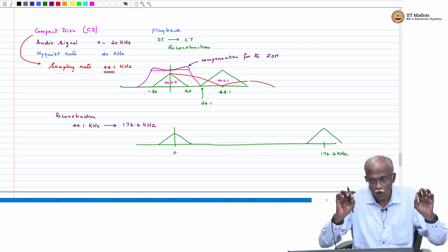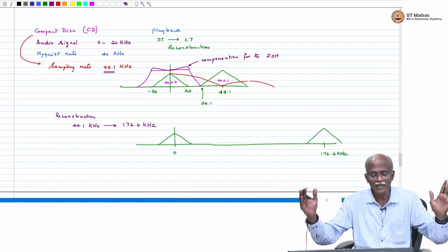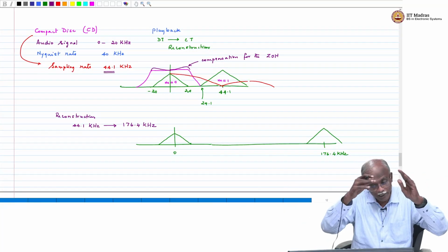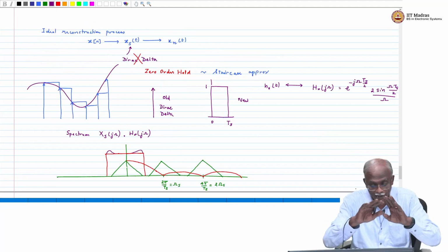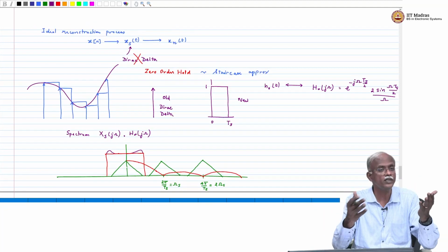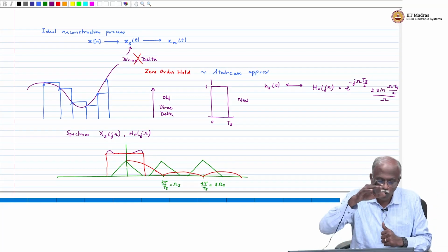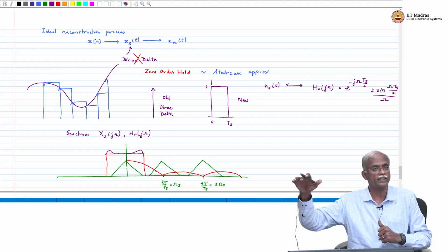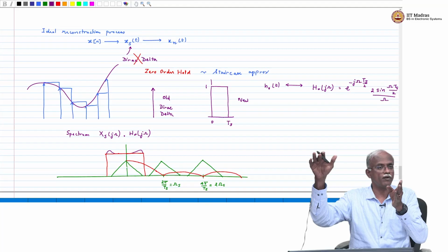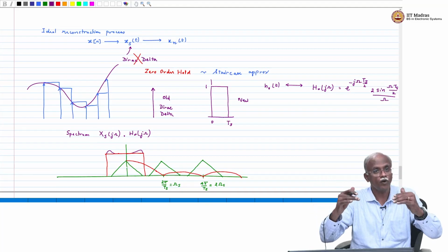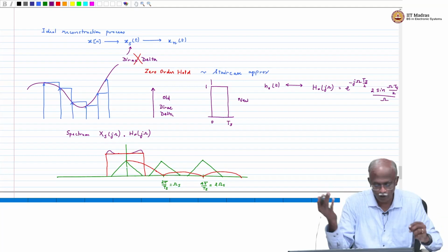Okay. So, why is it that we need this additional oversampling? For two reasons. One is you can build practical filters, and also in a practical reconstruction process, we cannot introduce Dirac deltas. So, those are more of a mathematical construct. So, what we can do is a peak hold detector, which is very easy to design. And so, you generate a staircase waveform, and then from the staircase waveform, you do a full reconstruction process through the convolution of the filter.